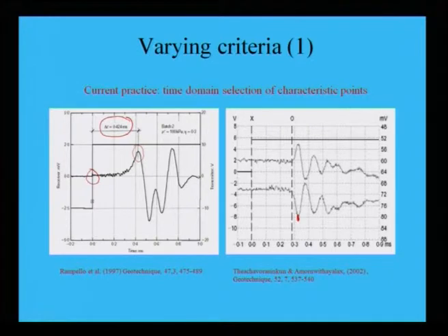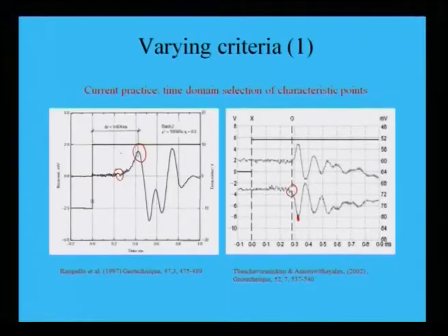Now, where will you choose your arrival time? There are different varying criteria. Shall I choose this point? As per another author in 2002, they have chosen this point as the arrival time, but here Rampello et al. 1997 have chosen this as the arrival time. Look at the difference. If instead of choosing here, I choose it here, the time lag will